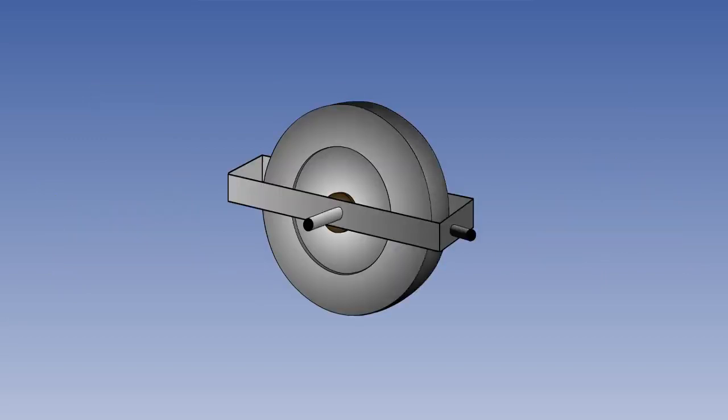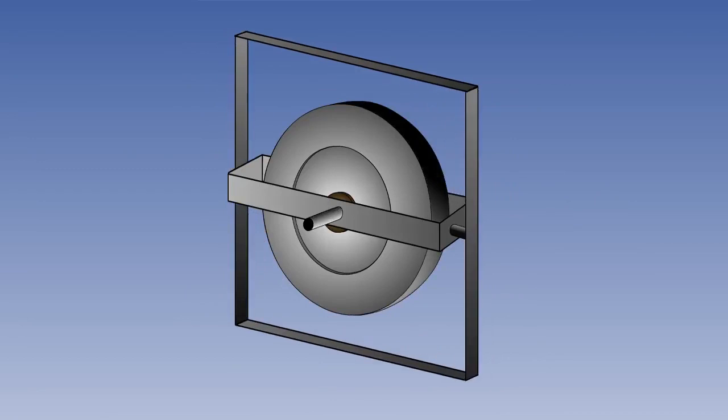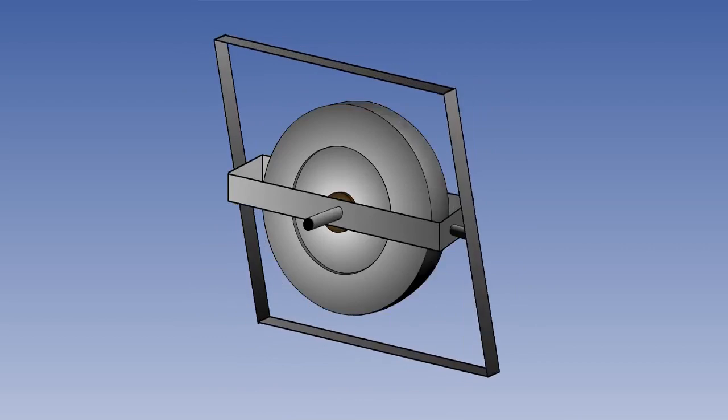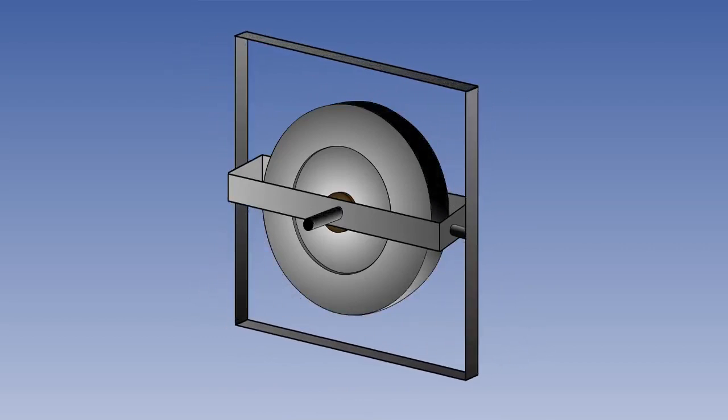The gyro is mounted on a frame, which we will call the inner gimbal. We can see that this will allow the gyro to rotate around its own spin axis. At each end of the inner gimbal there is a pivot point. We can see one here. The pivot point on the inner gimbal bears on a second or outer gimbal, and this gives the outer gimbal the freedom to rotate around the inner gimbal. The inner gimbal or single gimbal is therefore said to provide 1 degree of freedom.